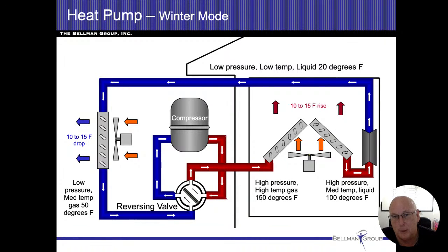And if anybody's ever dealt with a heat pump before, it's pretty difficult to say, is this thing actually working, you know? It's only a 10 to 15 degree temperature rise. So if I'm 70 degrees in a house, that means the air flowing out of there is going to be between 80 and 85 degrees. So if I look at my ductwork, the air that's going to be coming out of my ductwork is going to be about 80 to 85 degrees, all right?